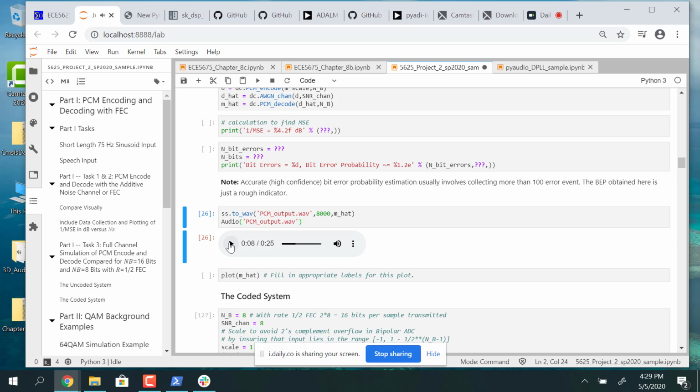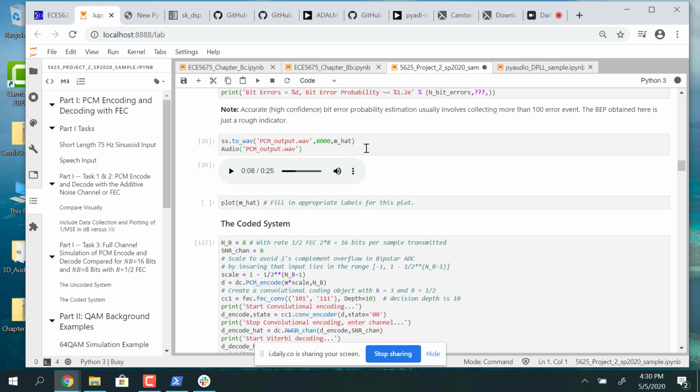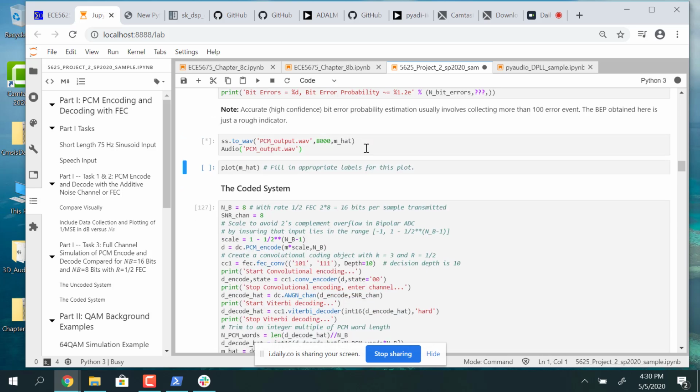So you hear that popping sound in there. Those are the bit errors that are occurring. And when we put in our Viterbi, it's going to clean that up. Or if I do the Viterbi scenario, which would be dropping that down to 6, just 2 dB signal to noise ratio difference in the channel, it's a waterfall shaped curve, as I talk about in the handout, things roll off really rapidly.